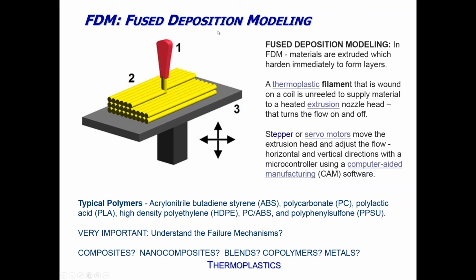Take the case of FDM, fused deposition modeling. So in fused deposition modeling, a filament of thermoplastic is heated from the head and then melt delivered or extruded on a nozzle. That nozzle then moves based on the programming of the apparatus to move in one direction and fill up layer by layer, okay, a build platform, which eventually moves to allow for the build-up of the object. But the big problem here is this type of printing produces a lot of failure based on the quenching of small layers or small printed material that is exposed to air.